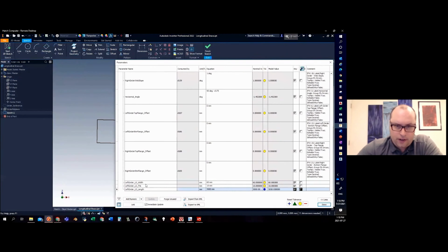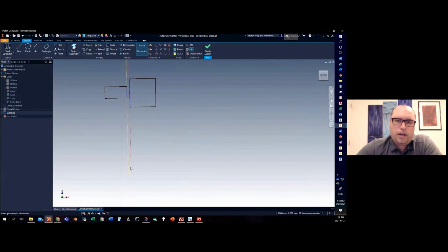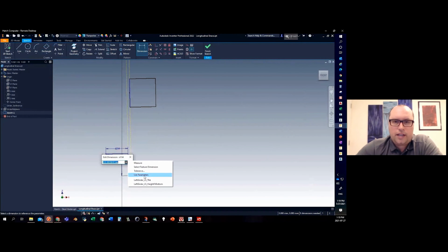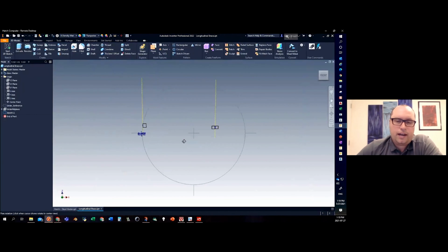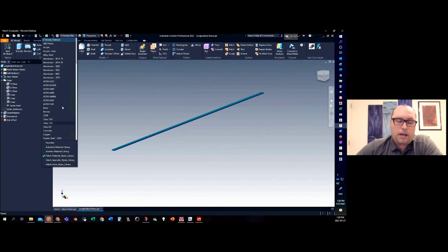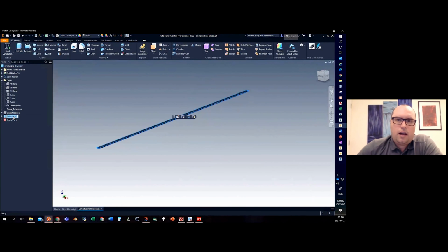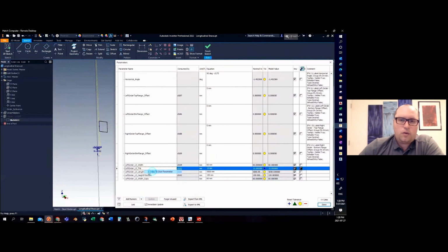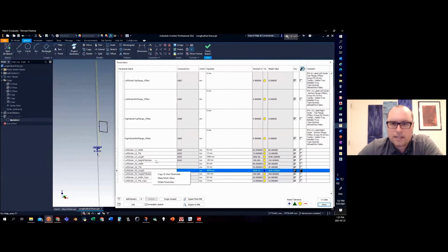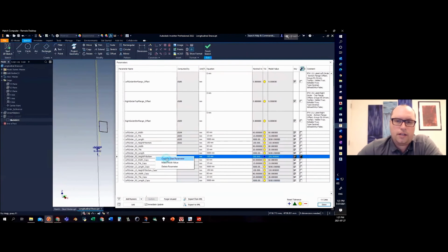It's unfortunate, it's different for every single type of component you're going to make. If you're going to make a girder, it's got rules to it. If you're going to make cross braces, abutments, piers, etc., you almost have to learn each one as a separate, different kind of trait. But in any sense, with Inventor, for anyone who's not familiar, you pick a plane, you put some sketches on it. You're going to create a bunch of different parameters, and then later you tie those parameters to the sketch. As you see here, you give them a bunch of different names, mark them as a key column, and those are what get exported into InfraWorks.